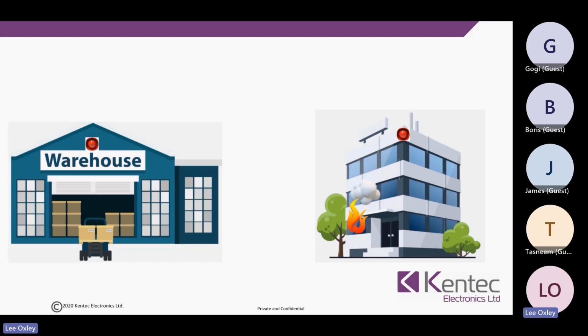So if there's a fire in the office building, you'd want that sounder to go continuously throughout the building to alert the staff so they can get out safely. But the adjacent building, the warehouse, you'd want to alert the staff in alert mode to warn them that there's an issue in the office building. So this is easily achieved by cause and effect programming in LE2, which I will go through next.